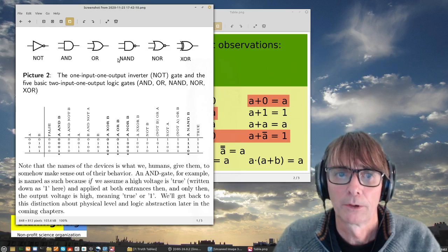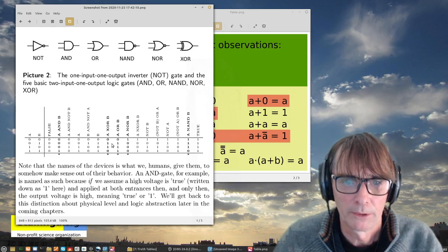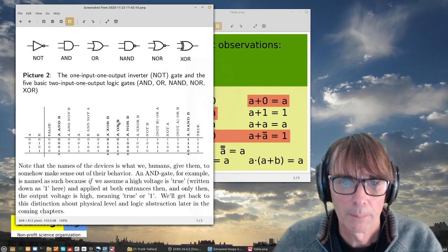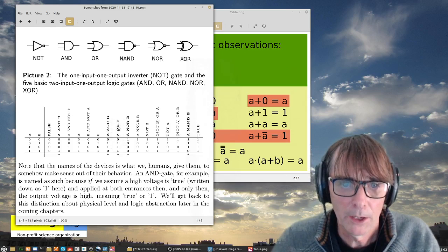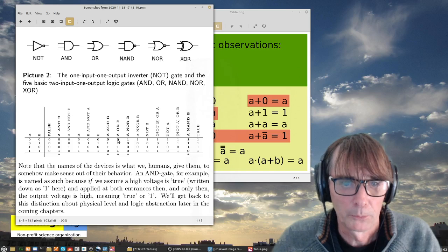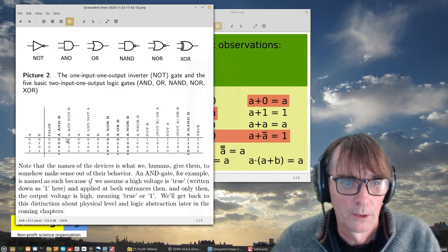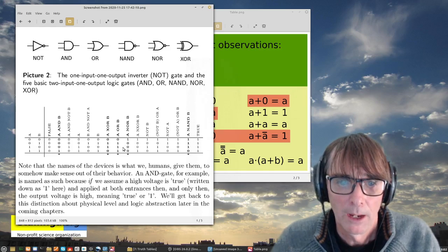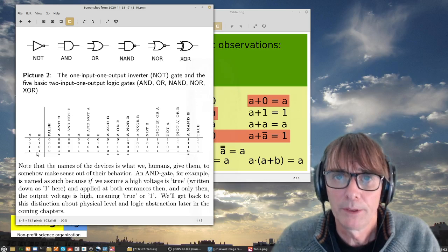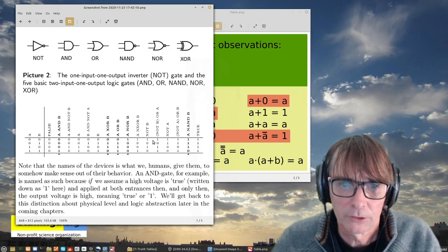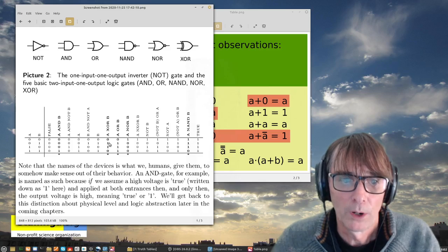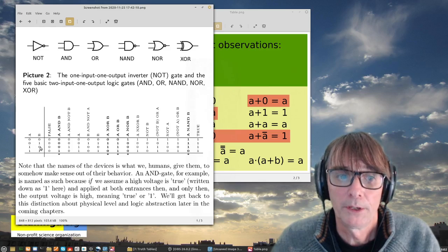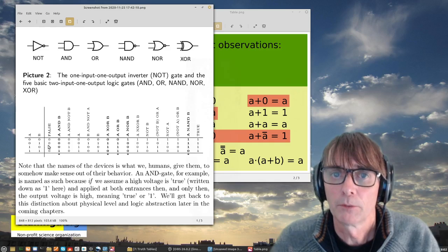That is very similar to the OR gate, except, let's compare it here. You have A or B, which is this column here. I hope that you can follow where I am. A or B. The output combination is 0, 1, 1, 1. 0 only when both A and B are 0, and it is 1 when both A and B are 1. And the exclusive OR, A exclusive OR B, is 1 when either A or B is 1, but not both.